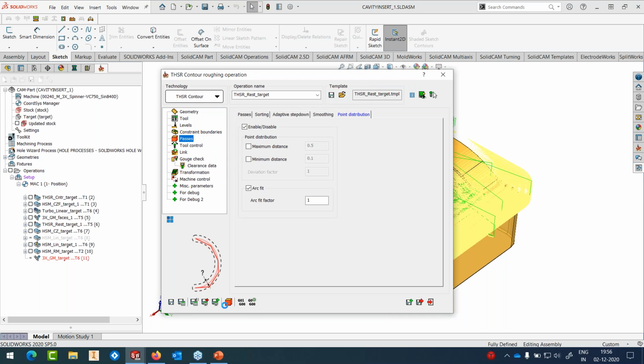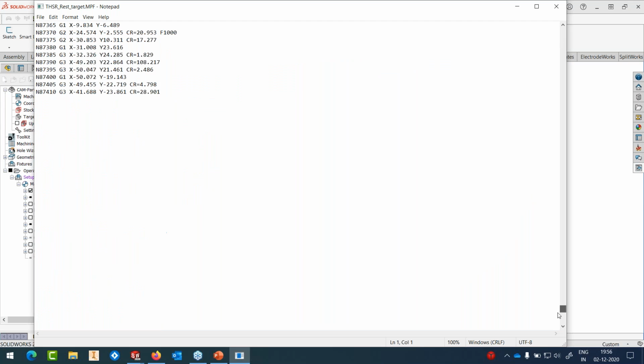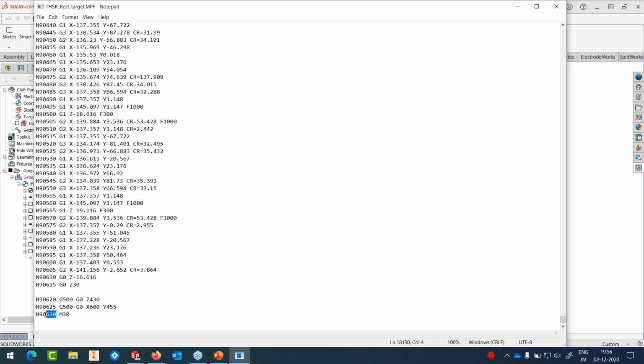And now if I generate the G code of this in 2021, it's just 90,000 blocks. It's 1/4. We reduce it to 1/4 by introducing arcs into our toolpath. This facility is now available with the entire roughing functionality and also the finishing functionality of Turbo. So we can fit arcs based on the tolerance that you use for machining. It's a very powerful function in 2021.